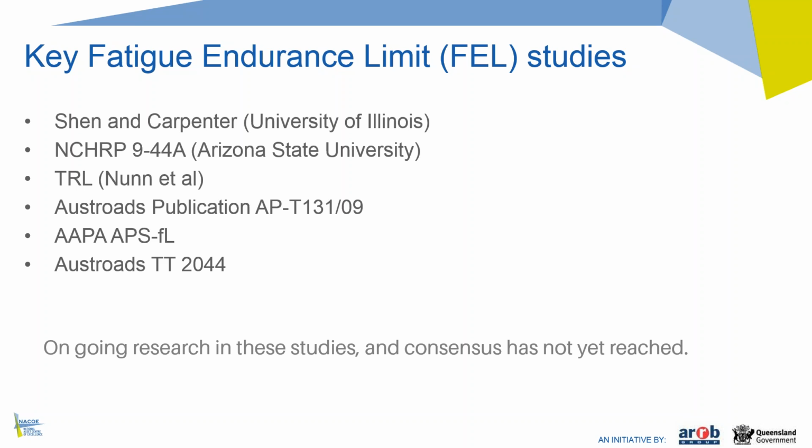The third study here was done by TRL in the UK. They carried out quite comprehensive field observation studies, and their conclusions again support the fact that when asphalt thickness goes beyond a certain limit, there's really not too much benefit.